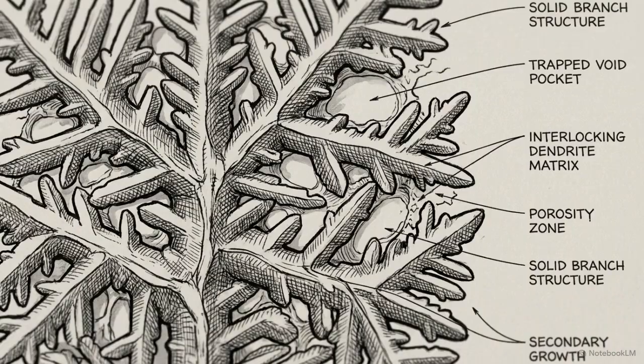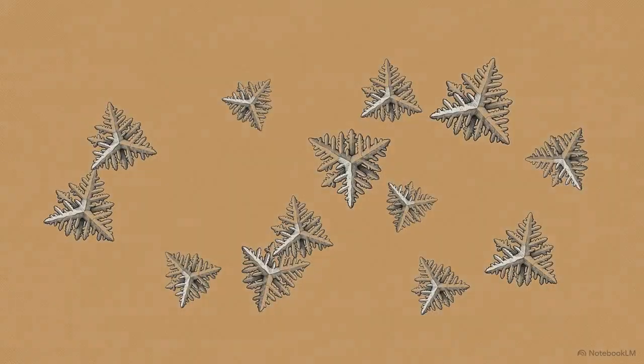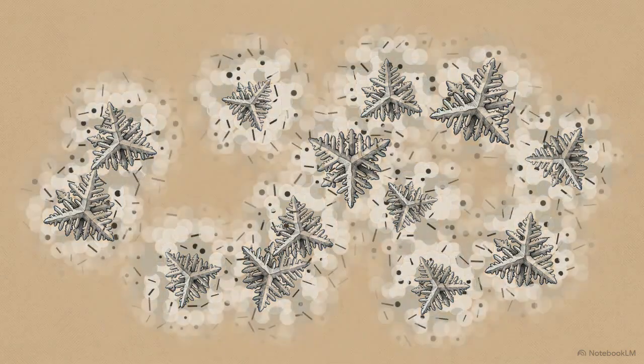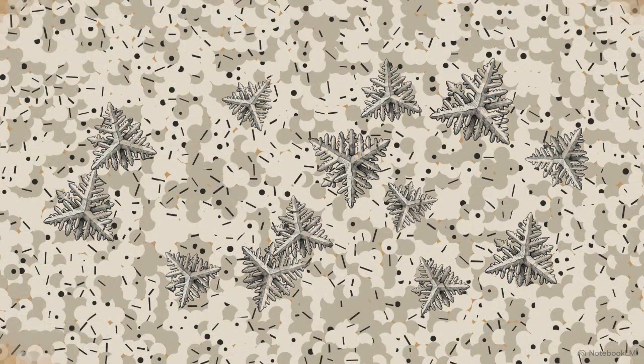As the alpha aluminum dendrites solidify, pockets of liquid metal remain trapped between the branches. To reinforce these gaps, HPDC alloys rely on a critical secondary element, silicon. This remaining liquid undergoes a eutectic reaction. This is a process where a single liquid simultaneously crystallizes into two distinct solid phases, in this case, a finely mixed dual-phase structure of aluminum and silicon.